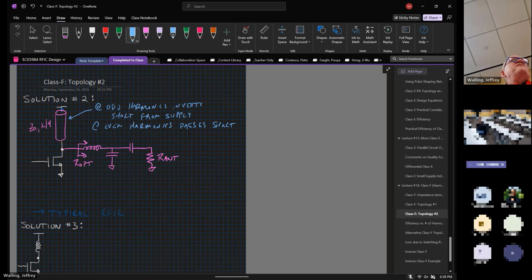We could probably make an artificial transmission line with a couple of wire bonds. So if we have the center bond and then the 2 down bonds, that can make kind of an artificial transmission line. But then you're really playing around with how precisely they can control just the geometry of the bond wires, right?